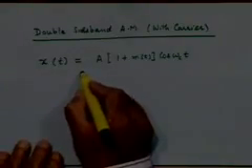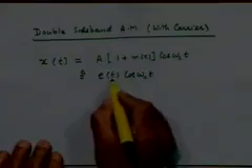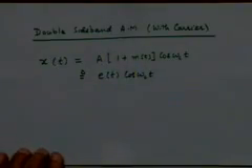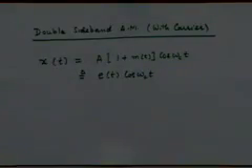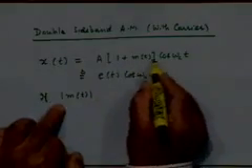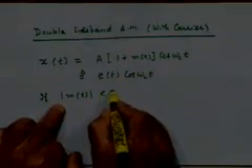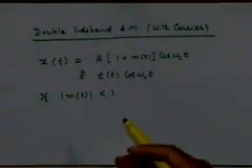And let's define this as some e of t times cosine omega ct, where e of t is defined as A times 1 plus m(t). Now let's look at the time domain behavior of this waveform. It can be made to have a very interesting property under a certain condition. For example, if I ensure that the magnitude of the message waveform in this equation is always less than 1, right? Think of this as 1 volt and m(t) lying between minus 1 volt and plus 1 volt.